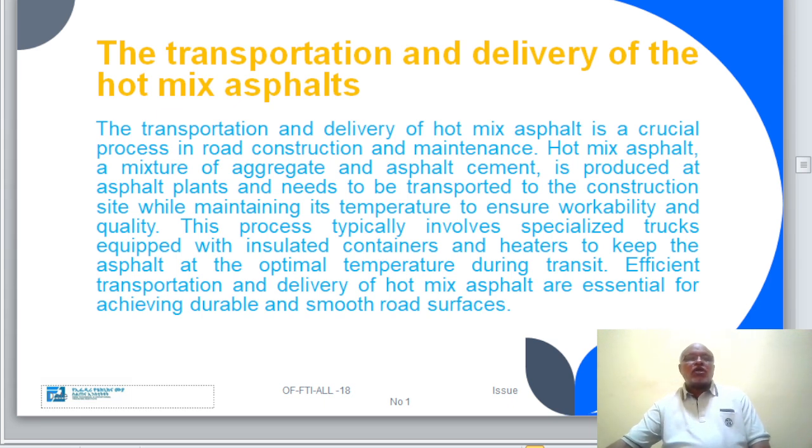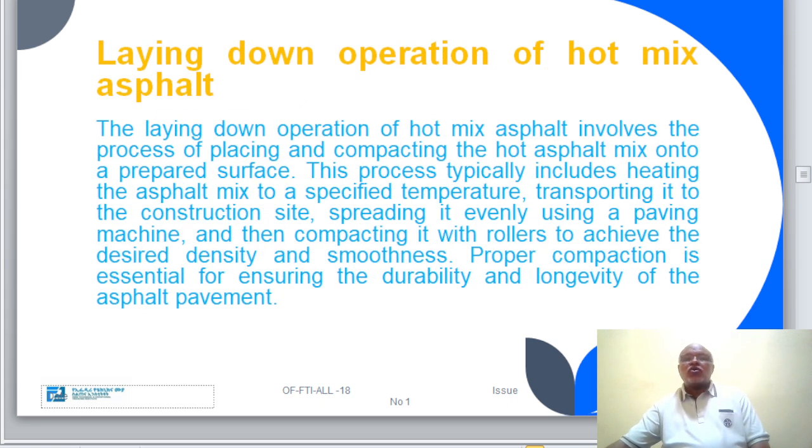Laying down operation of hot mix asphalt. Laying of the hot asphalt is carried out with special motorized units called pavers. Pavers are available in a wide variety of sizes capable of laying mats from as narrow as 1 meter to up to 16 meters wide. The minimum and the maximum range of paving widths vary from one manufacturer to another.